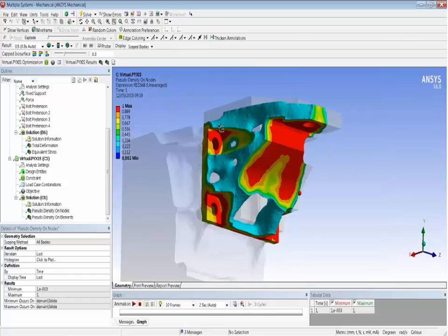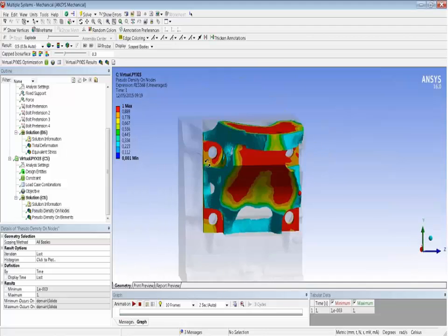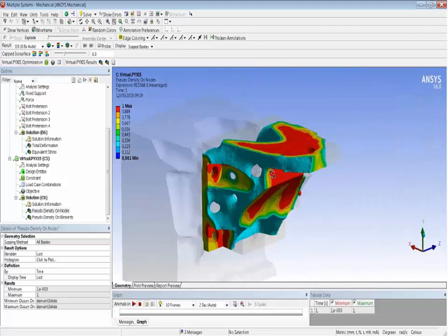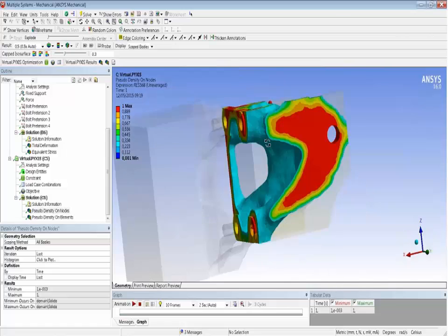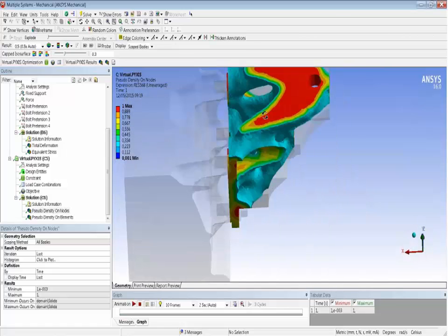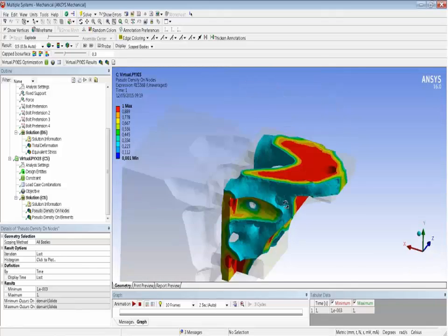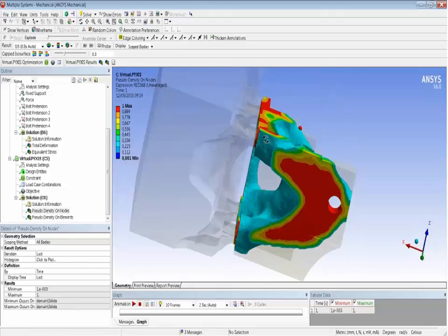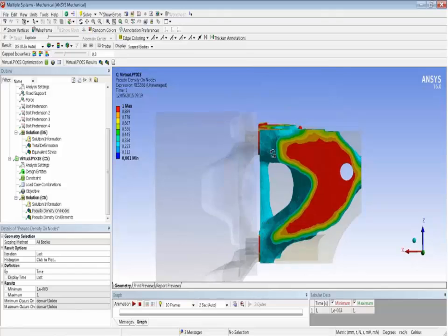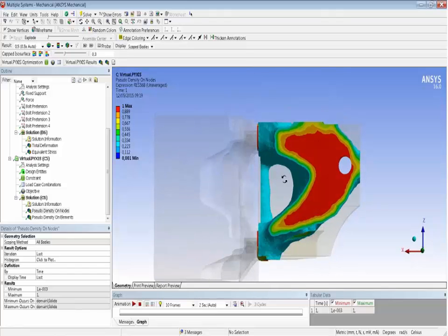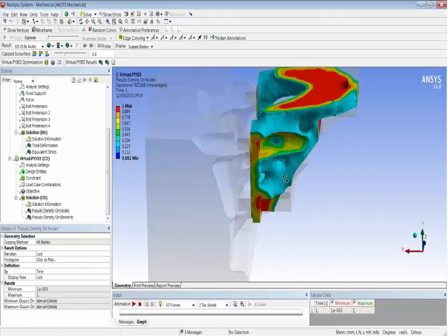Also, you see red regions of material around the main member of the structure and around the bolt load, both regions. And you see more or less the shape where you can control, for example, in the next run, the manufacturer. In this case, for example, you could also have an opening for this direction and Y, for example.